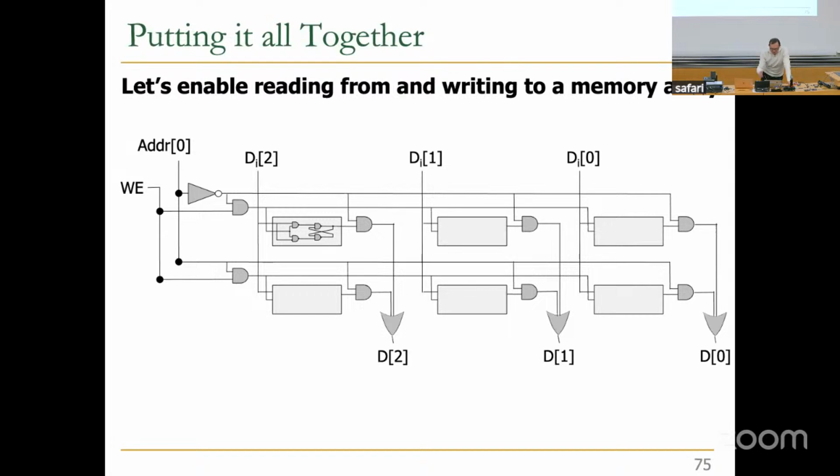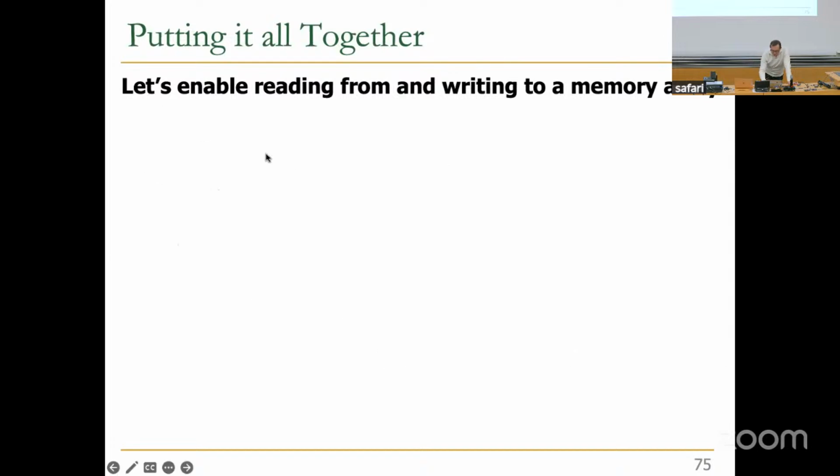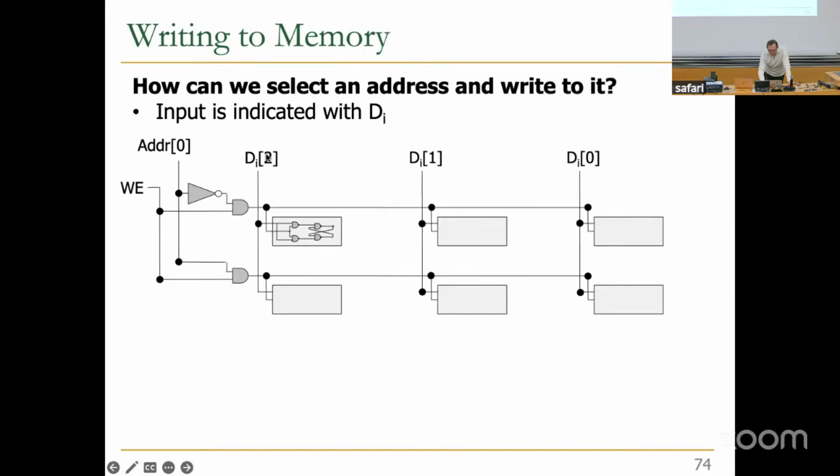Actually, I've shown you this already. But you need to have a data input. I kind of showed you the data input also, actually. This is the data input that you write with the write enable signal. And this is essentially our gated D latch from earlier. So it operates exactly as we said. If you're writing to address 0, then this input D gets transferred into the output of the D latch, which is whatever is over here, Q essentially, but it's not shown over here.